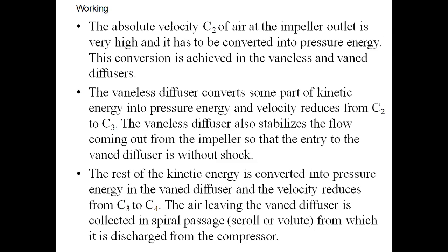The rest of the kinetic energy is converted into pressure energy in the vane diffuser and the velocity reduces from C3 to C4. The air leaving the vane diffuser is collected in a spiral passage from which it is discharged from the compressor.